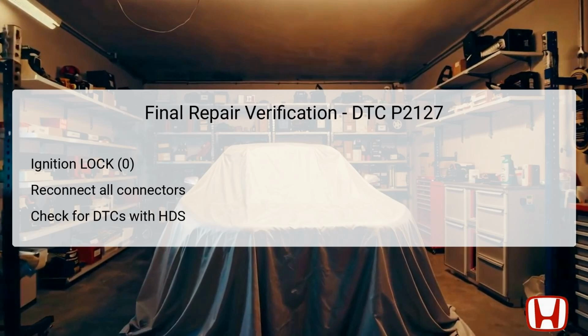The final repair verification process begins by ensuring that the ignition switch is turned to lock 0. Reconnect all previously disconnected connectors systematically to restore the vehicle's wiring integrity. Once all connections are secure, turn the ignition back to the on second position. Utilize the HDS to reset the ECM and perform the ECM idle learn procedure so that the system can adapt to any changes made. After completing these steps, check for any pending or confirmed DTCs with the HDS.